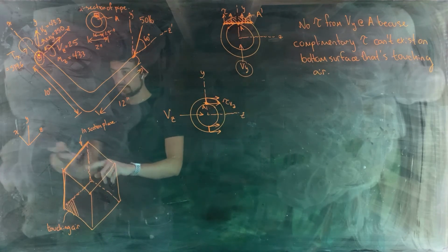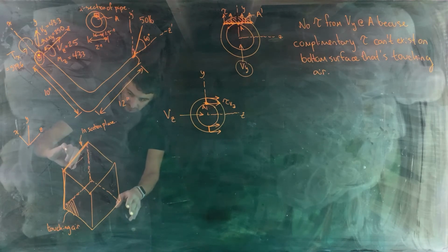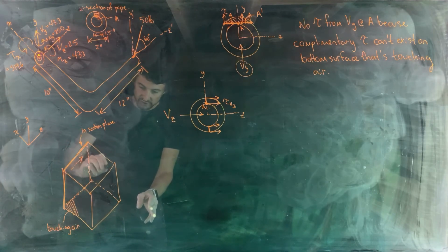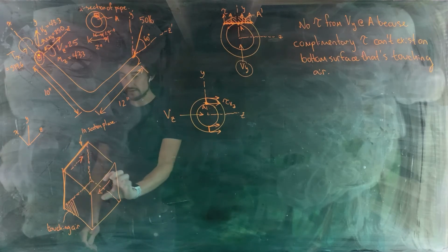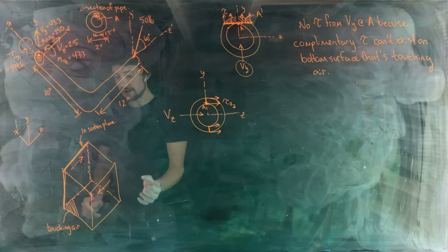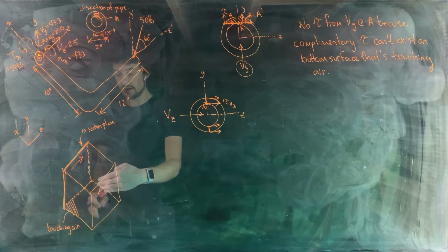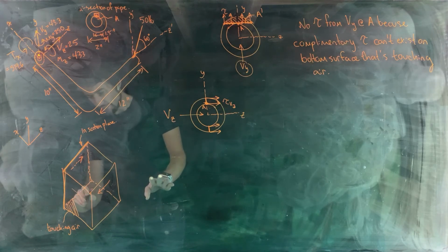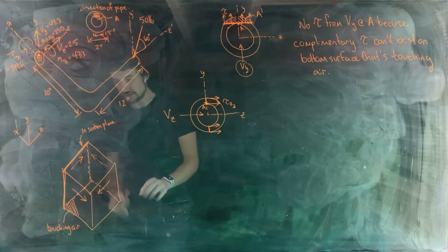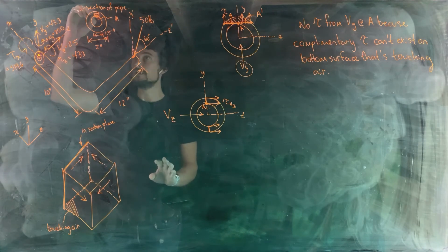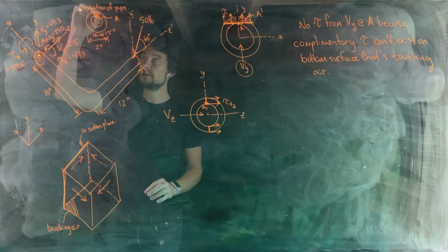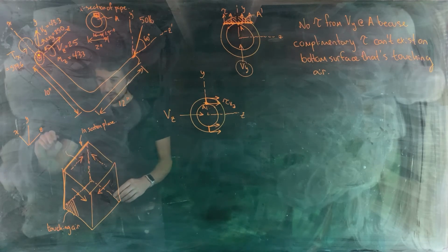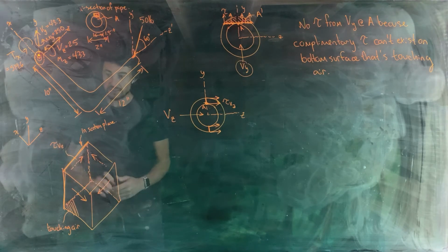So go to your face, positive Z direction, place a shear stress that is in that direction on that left-hand face. And then again, let's place the other shear stresses that have to be there. One shear stress on the back face, okay? That's around the right-hand face. That shear stress is fine because we've got a material-to-material connection between this small element and the next one that exists, and then we need a shear stress like this and a shear stress like this. And again, those are both fine because those shear stresses occur along an edge where there's a material-to-material connection. So all fine. So this one here is getting labeled tau VZ.